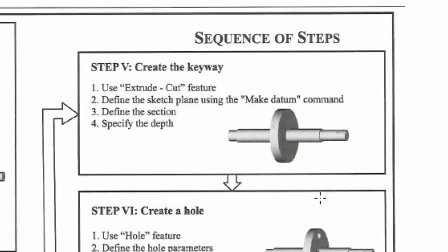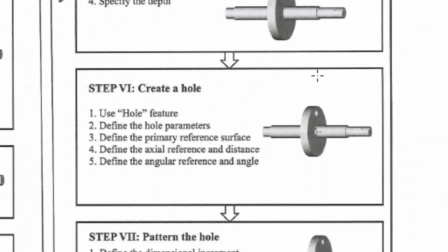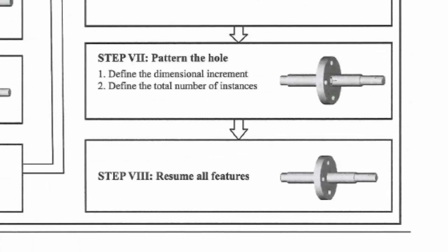Step 5, create the keyway. Step 6, create a hole. Step 7, pattern the hole. Step 8, resume all features.